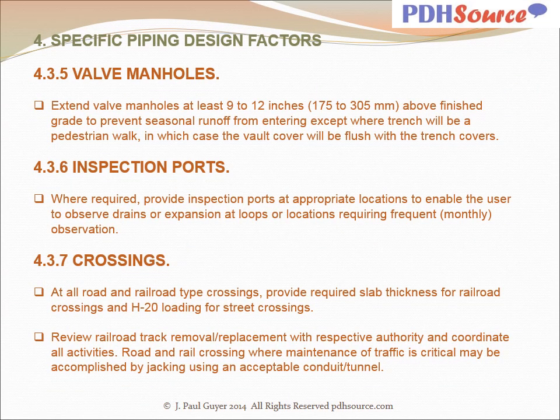Extend valve manholes at least 9 to 12 inches above finished grade to prevent seasonal runoff from entering, except where trench will be a pedestrian walk, in which case the valve cover will be flush with the trench covers. Where required, provide inspection ports at appropriate locations to enable the user to observe drains or expansion loops or locations requiring frequent, say monthly, observation.